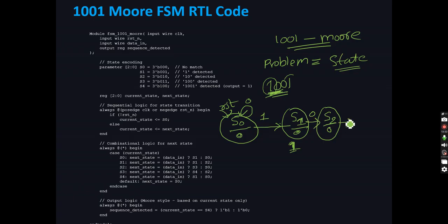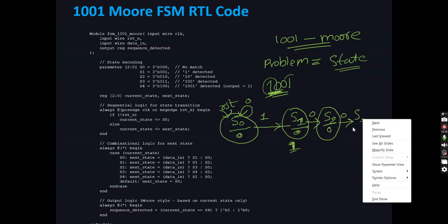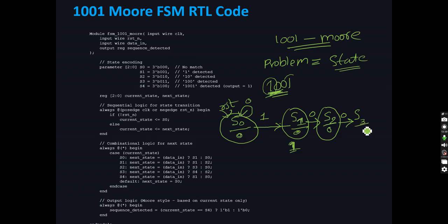First detect all the states. So again I'm giving 0. Let's take this state as S3 and the output is 0 only. Why? Since it's not detected fully. So this is the state of 1 0 and this is the state of 1 0 0. And again I am giving 1. So at last our main state came, the last state, which is able to detect the 1001 sequence.